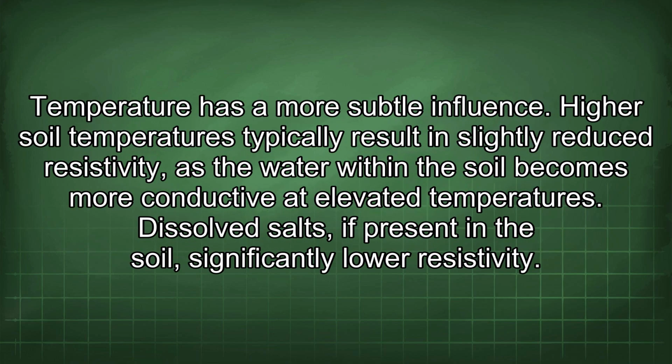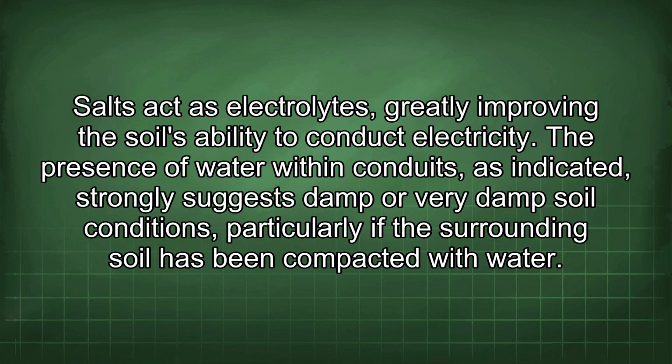Temperature has a more subtle influence. Higher soil temperatures typically result in slightly reduced resistivity, as the water within the soil becomes more conductive at elevated temperatures. Dissolved salts, if present in the soil, significantly lower resistivity. Salts act as electrolytes, greatly improving the soil's ability to conduct electricity.